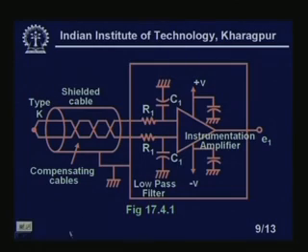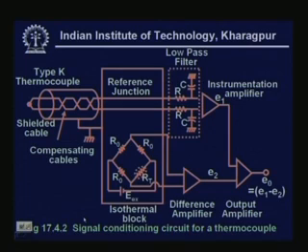So let us look at it. This is our complete circuit diagram. You can see here, this is a type K thermocouple, which we have already shown. This is the figure, circuit 1 and circuit 2. This is E1, the output voltage; it is not cold junction compensated. We have a reference junction, which we now put on an isothermal block. You see here, and this is the circuit which I have used just now.